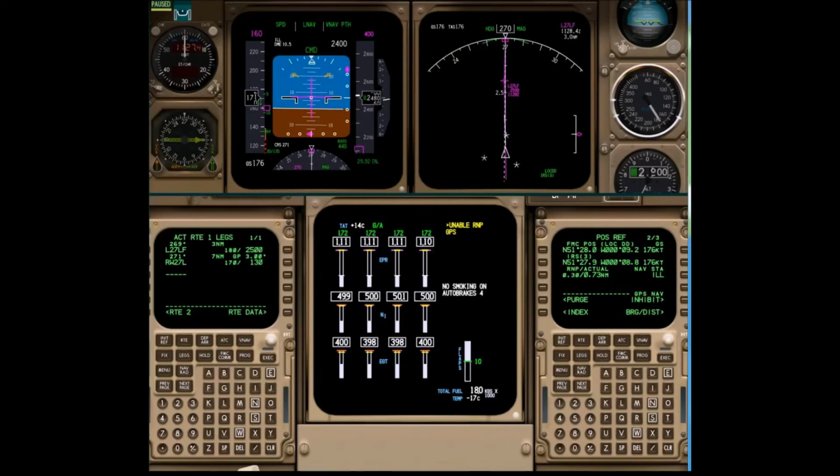If the ANP exceeds the RNP at any stage, you will get an unable RNP message. On the approach, if you're not flying an RNAV, this need not be a disaster. You can continue to fly the aircraft on raw data, and as long as you are within the normal limits for a non-precision approach, that's fine. It's not possible to continue an RNAV approach like this, however.